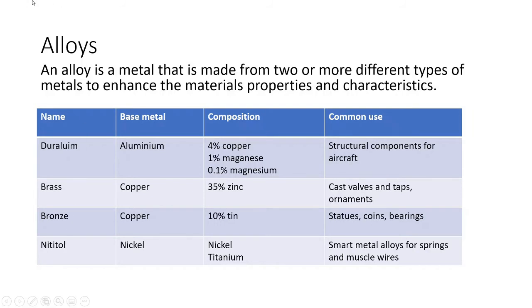Nitinol, you will see that in the smart materials videos as well. That is the metal that essentially you can bend and deform, and then you can apply heat to it or sometimes electrical current, and it will snap back into place. There was a big trend in the 2000s where people had glasses frames made from them. So if you sat on your glasses, you could heat them up and they would snap back into place. They're used in things like train tracks for dental work, because over time, when it reacts to the body heat, it snaps those back into place. Same with if you've ever had pins put in your arm, they can use that because it reacts to the body temperature, so it will slowly start to set the bone back in place as well.